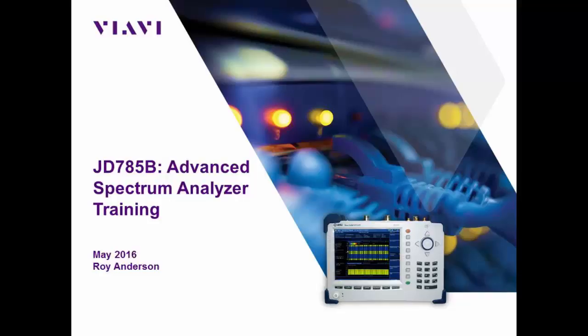And then I want to spend a little bit of time talking about what a spectrum analyzer, specifically a swept spectrum analyzer, is and how it works, and how the different measurements that you can make on it, power measurements specifically, are done. And then we'll talk a little bit about a swept versus an FFT analyzer, which actually the JD785B is both of those. It's two different spectrum analyzers in one.